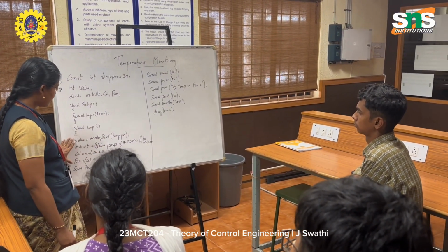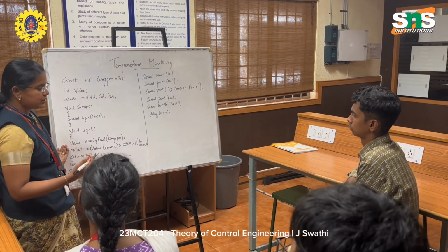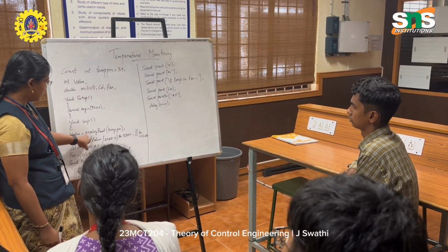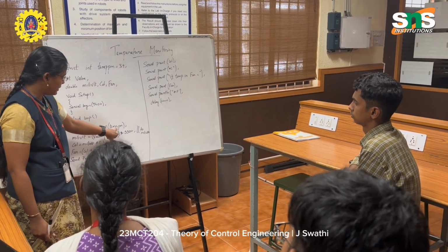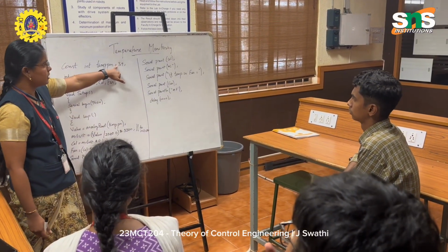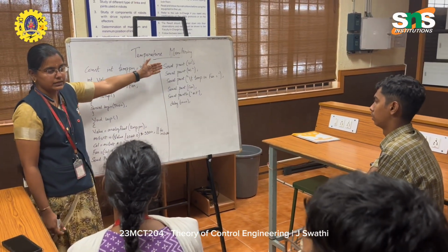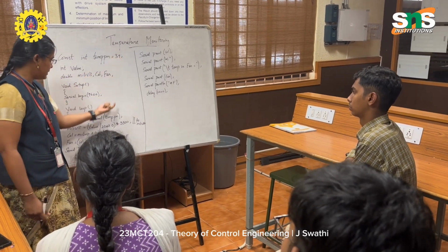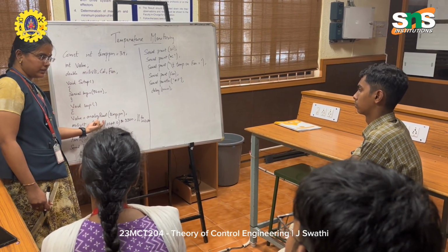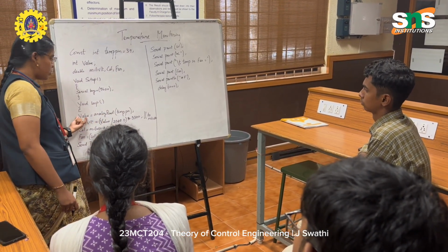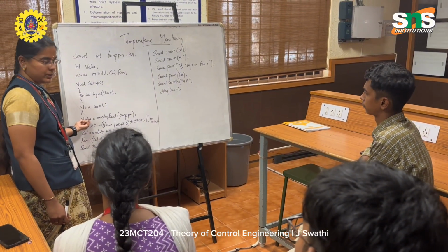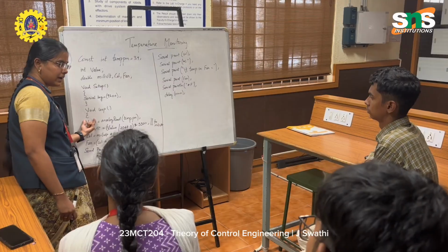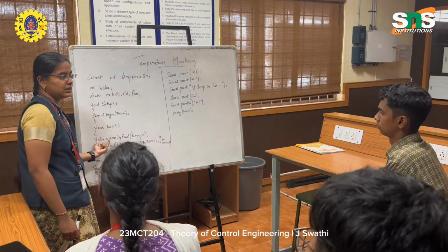In the loop, I am going to add a few instructions, like value. This value is nothing but analogRead from the temperature pin. From the 39th pin, I am going to read the temperature from the real world. Through this pin 39, I get the real world analog data, and that analog data will be stored in my value variable. Next, for the millivolts, I am going to convert this value into a voltage value, that is in millivolts.